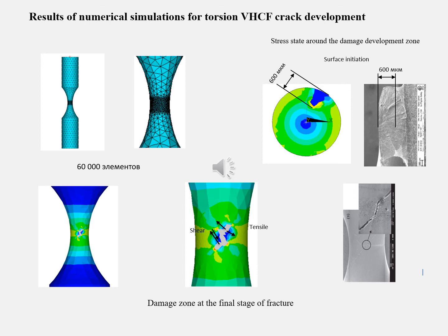Moreover, here we have a lateral surface of the specimen, and we see that the model predicts the crack initiation in the plane of maximum shear stress, with further bifurcation to crack propagation in the plane of normal crack. And the analysis of the criteria that destroy the elements shows that at the beginning it is shear stress that leads to the fracture, and later the crack propagation is related to the normal crack opening.